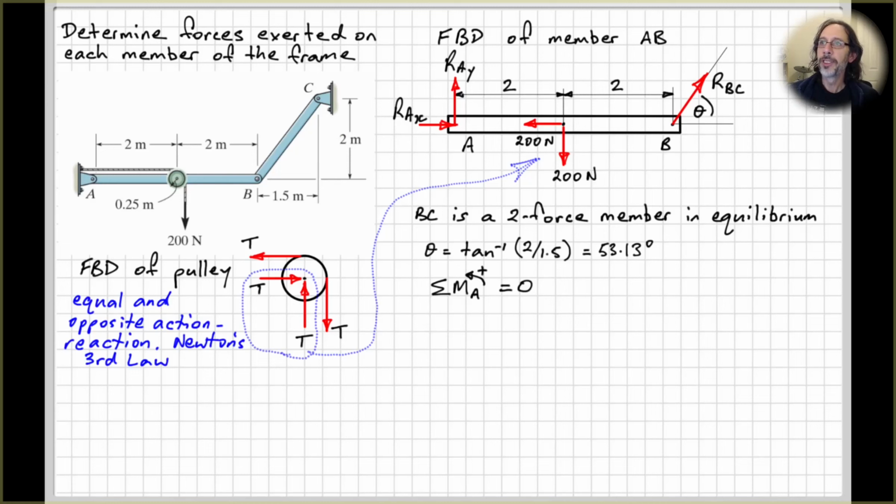So if you take moments about point A, so usually in an equilibrium problem, we'll start with taking moments about a certain point, because that will generally enable us to find one of our unknowns straight away, assuming we choose the right point here. And the point to choose is a point where 2 of our unknowns pass through, right? Because that removes them from the moment equation.